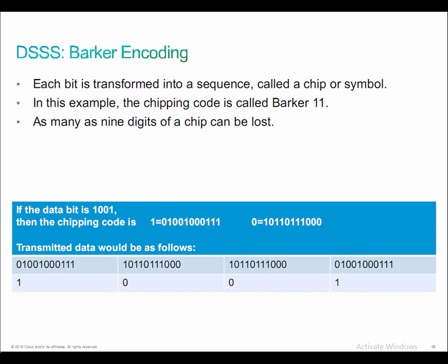In other words, without considering any kind of specific technique, a 2 megahertz wide signal allows about 1 megahertz of useful data to be sent. So there's an overhead, and then there's loss and other things that will occur. So we're going to get about half of the signal is going to be useful for data.